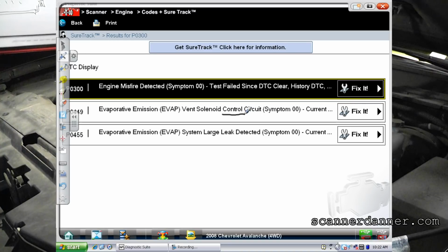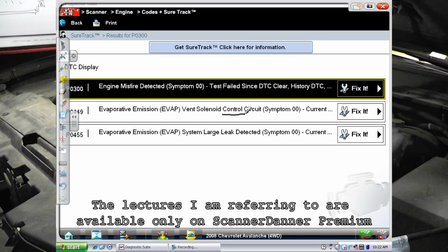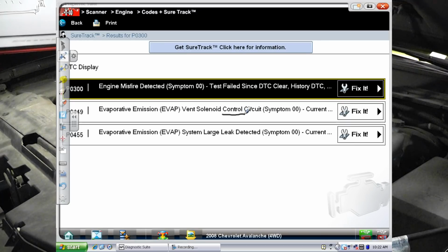Section 3, we talked about output solenoids, and we talked about the output state monitor. You remember that discussion? Voltage is high when the circuit's off on a ground side switch. Voltage is low when the circuit's off on a power side switch. Computer knows that. It's looking at those voltage levels. I believe that code is coming from that.